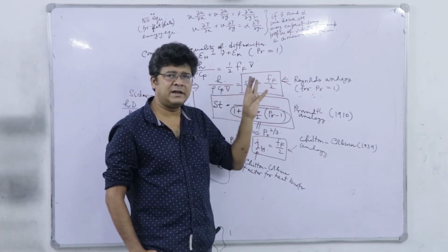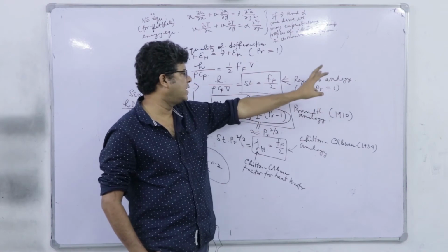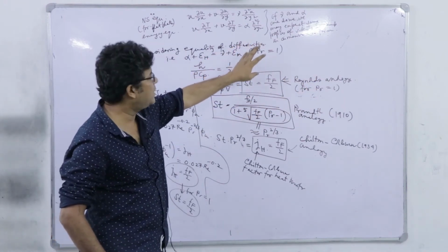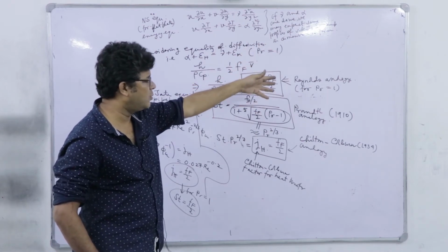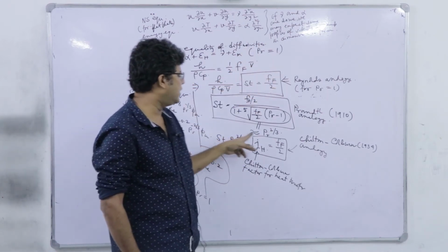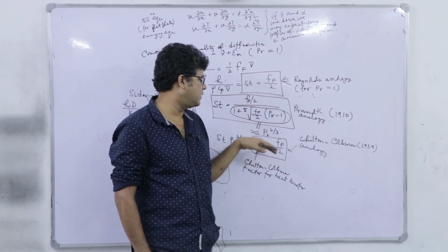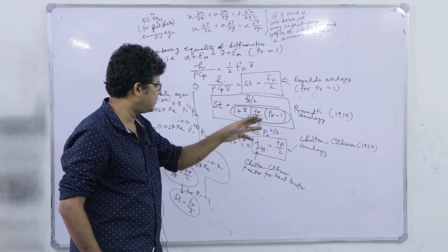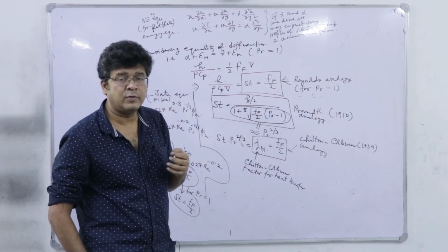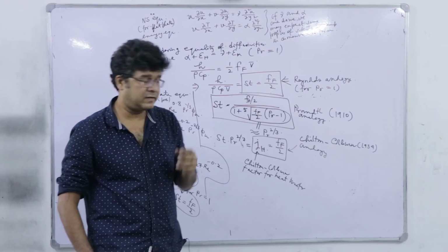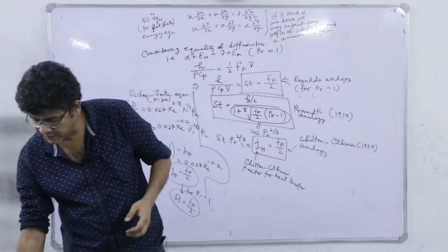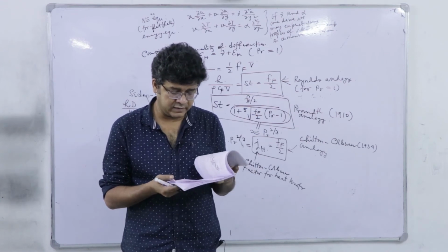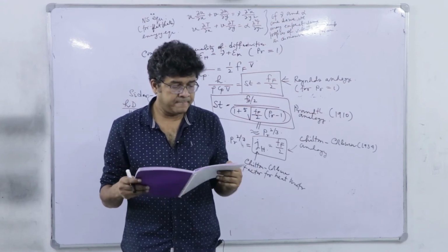Reynolds analogy nowadays is simply of historical importance and valid for Prandtl number 1, that is valid for air. Okay. Air has got a Prandtl number equal to 0.7, close to 1. So, Chilton-Colburn analogy we majorly use, and that is why this Chilton-Colburn factor has been tabulated with respect to Reynolds number in different design books. We will discuss that when we go for heat exchanger. Next. So, that is about the analogy of heat and mass transfer, or this heat and momentum transfer.